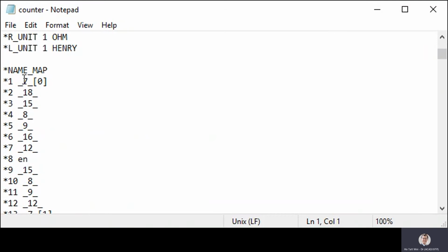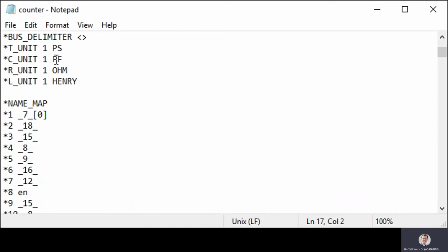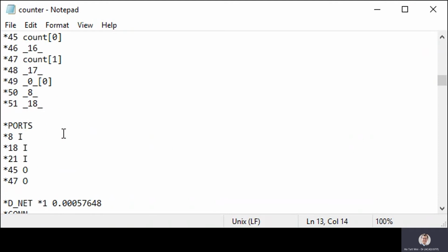And I'd like to now draw your attention also to the SPEF file. So the SPEF file, let me just quickly open it up, contains the parasitic resistance and capacitance parameters. Okay, so you can see this is a mapping of individual node names to a shorter reference within the file itself. And here are the basic units of capacitance in femtofarad, resistance in ohms, inductance in henries.